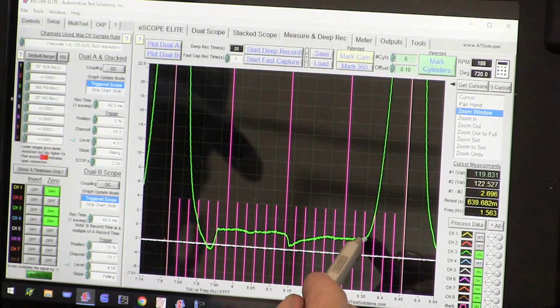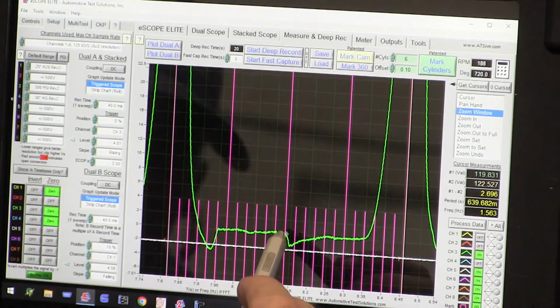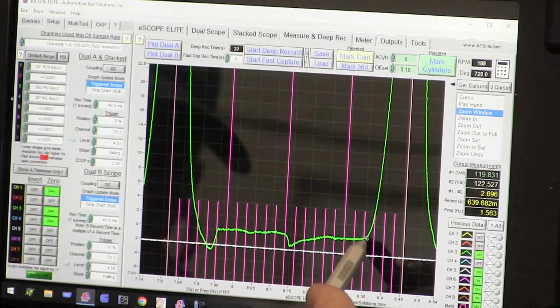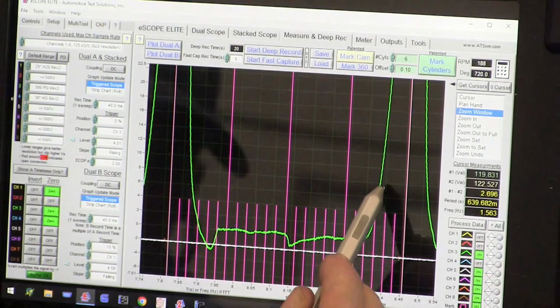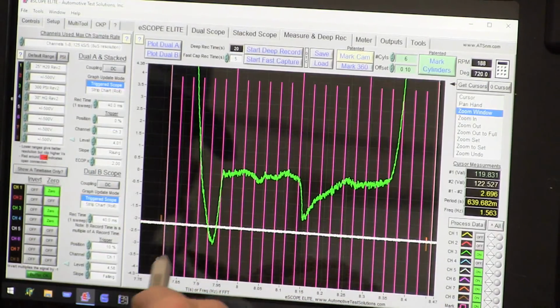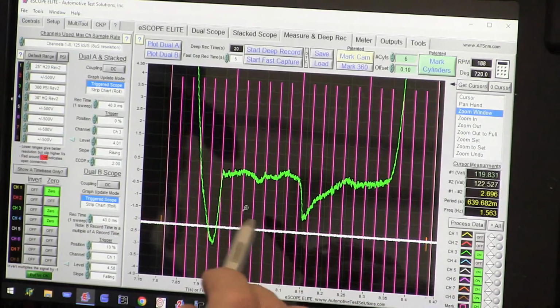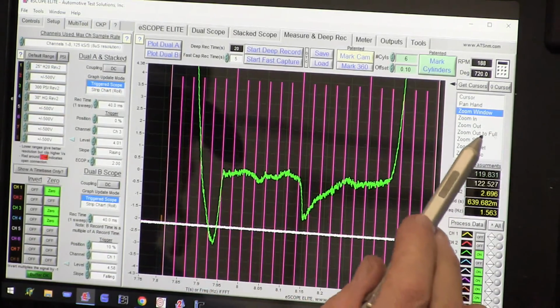And I close the valve at 60 after top dead center. And that's our bottom dead center. And that's what I'm expecting. So again, the valve opens at about top dead center and I get my drop down. I go across and I go 30, 60 after bottom dead center, about 60 degrees, and I go up. So again, these look real good now. This is about what I would expect, but when it's running, it's way advanced, but when we're cranking, it's not.